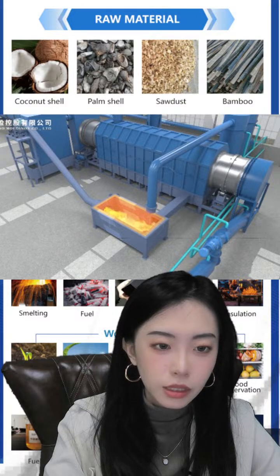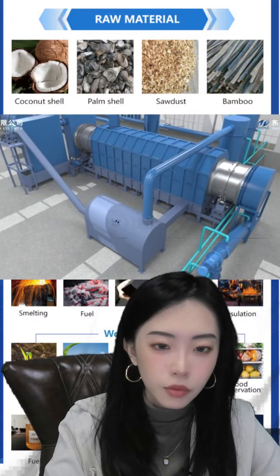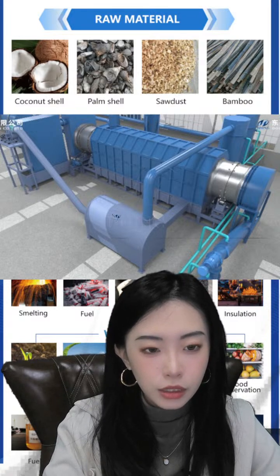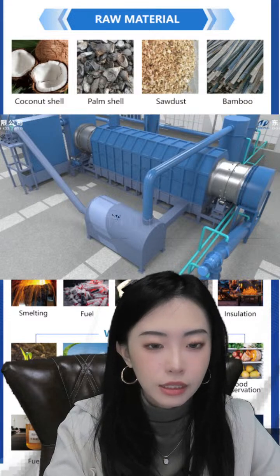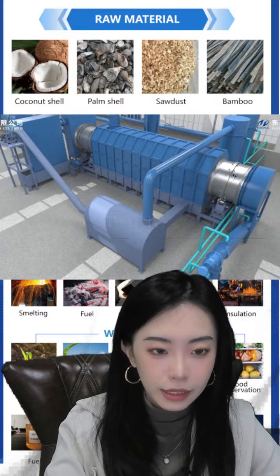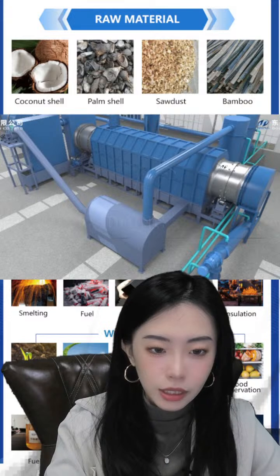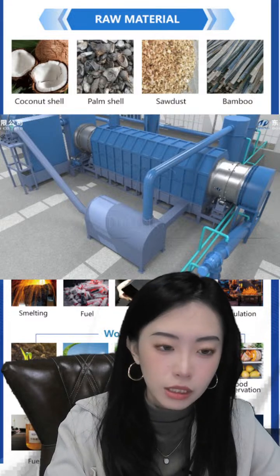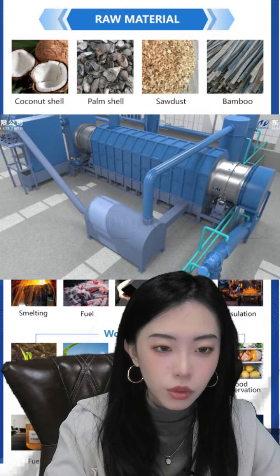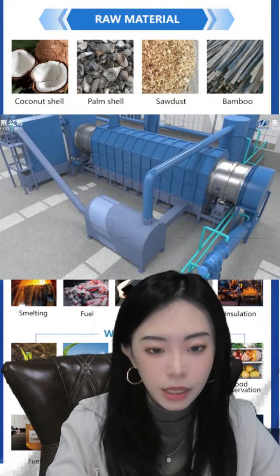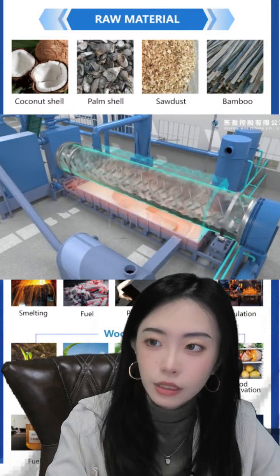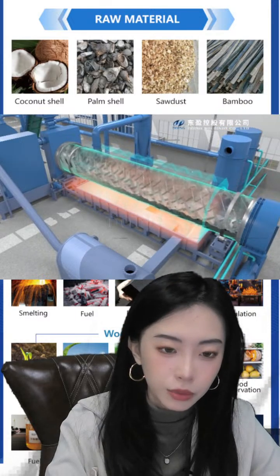And for heating, we use hot air furnace heating here. The equipment uses indirect heating. The furnace chamber is at 400 to 600 degrees, and the temperature at the front end of the furnace chamber is higher than the back end. The section at the back is empty without an installation cover, in order to cool down the material by the normal temperature. You can see here indirect heating by using this hot wind.